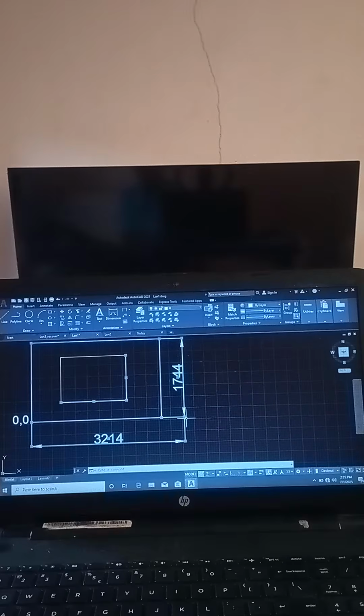And that selects everything. Whatever you touch goes on. Now, anything that is selected means it's a complete element. For instance, if I click on any of these arrows here, it will select anything that has to do with it because it's actually from a dimension. Otherwise, you won't select that. So in this type of selection, you select by moving from right to left, and that is called cross window selection.